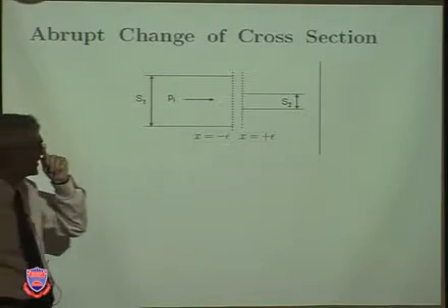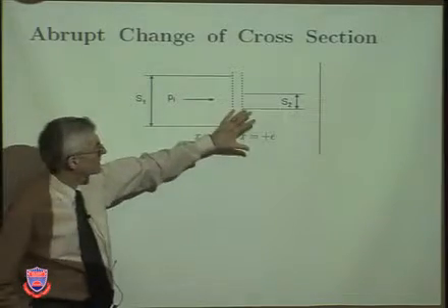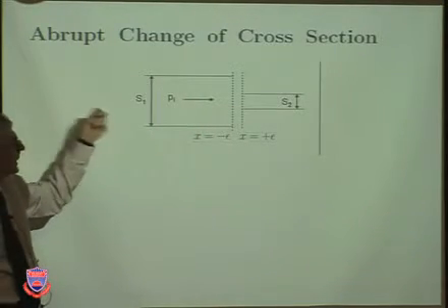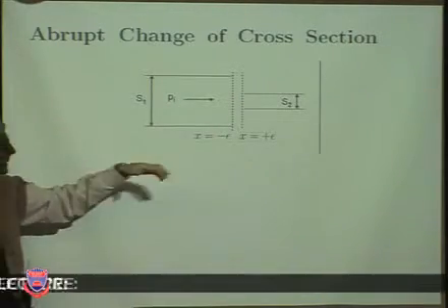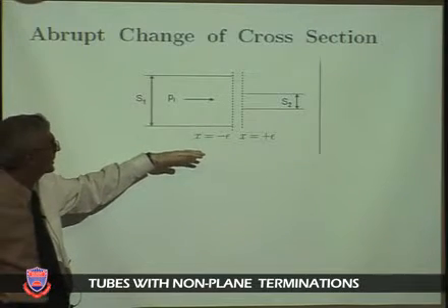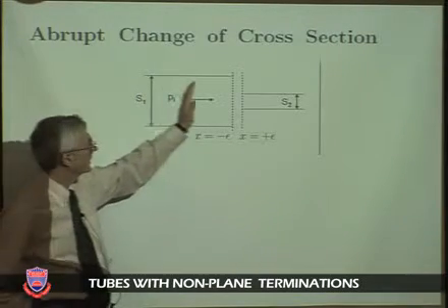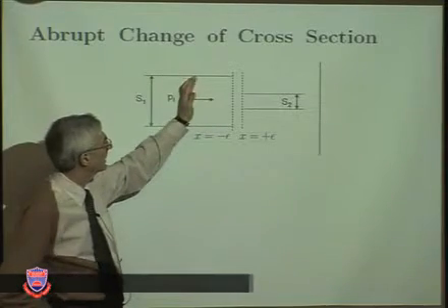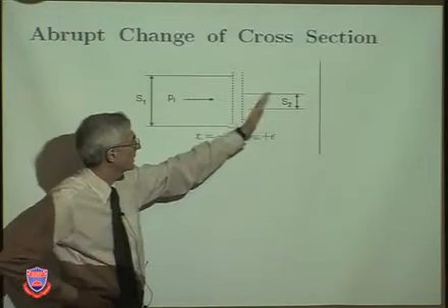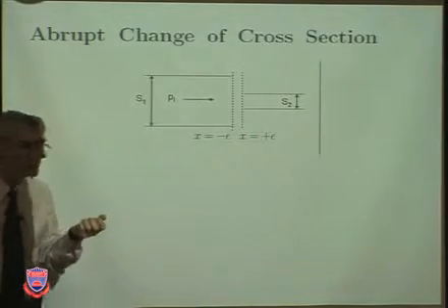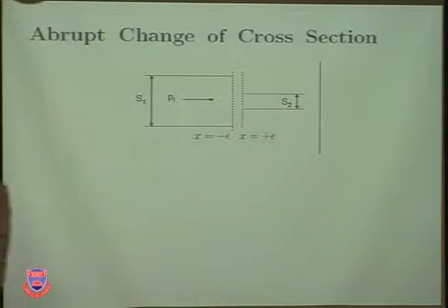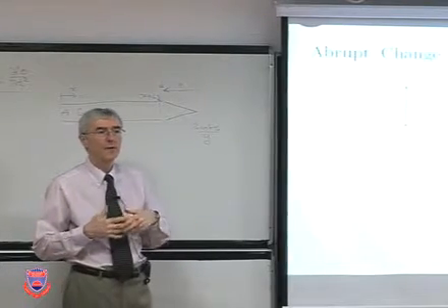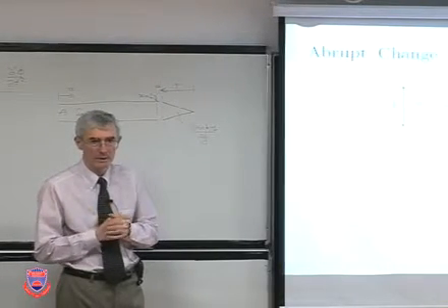We went over this roughly, but this is the basics of what happens when there's an abrupt change of cross-section, okay? In trying to develop this equation again, as plane waves go from one duct or pipe into another one that has a different cross-section, of course, in an area that's just around the intersection, there will be unusual wave shapes, waveforms that will develop.